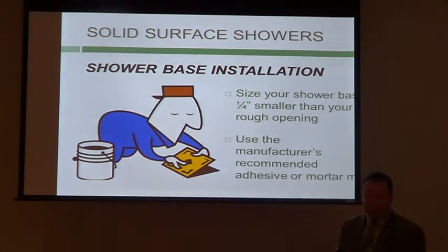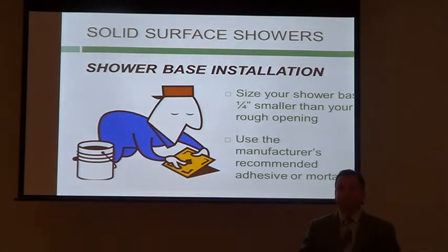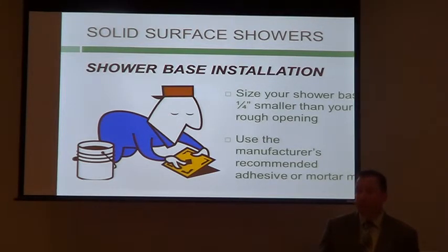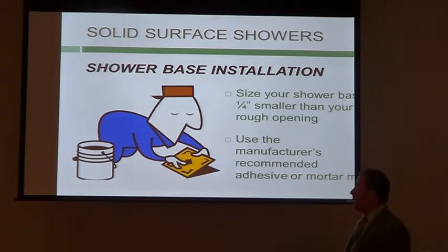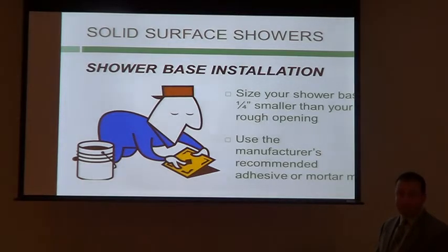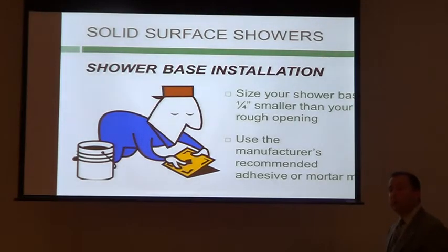The shower base. Shower bases typically manufactured with a flat base. Okay? Now, you would think that the floor, whether it's new construction, would be level. They rarely are. So the takeaway here, and I know you're not installing these, but they need to be mounted level. Kind of goes without saying, but so that if you need to shim it, all manufacturers recommend a thin set mortar to fill in the voids and to allow the panel or the base to be seated into that mortar base. Okay? That also gives you no voids underneath, which lends itself back to that durability we talked about.